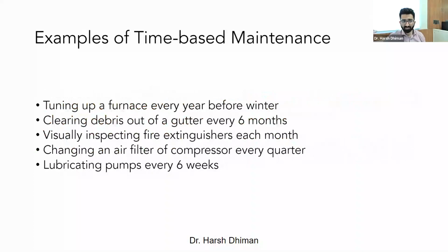So what could be several examples? Let's say tuning up the furnace every year before winter. You could change the properties of the furnace. You can clean a furnace, right? Cleaning debris out of gutters every 6 months. Yes, that is something that we see on a day-to-day basis in our localities and neighborhoods. Visually inspecting fire extinguishers each month. If you have fire extinguishers installed in your factory or plant, you can have a visual inspection. Changing the air filter of a compressor every quarter. Again, yes, people do this quite often, because sometimes these places are inaccessible.